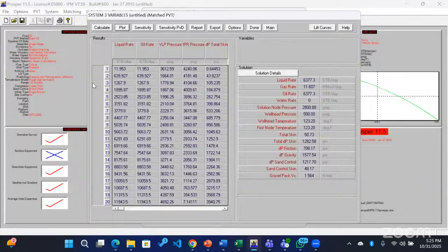Then another thing I want us to do is, okay, we've chosen this gravel pack permeability. So Prosper will allow us to model, like, okay, let's choose the best. It will help us to have varieties of options. And how do we do this? Through system sensitivity analysis. So we want to have different kinds of scenarios of our gravel pack so that we know, okay, this is the best we are going to go with. And we'll go from there. I think that's the last thing I'll be doing here.